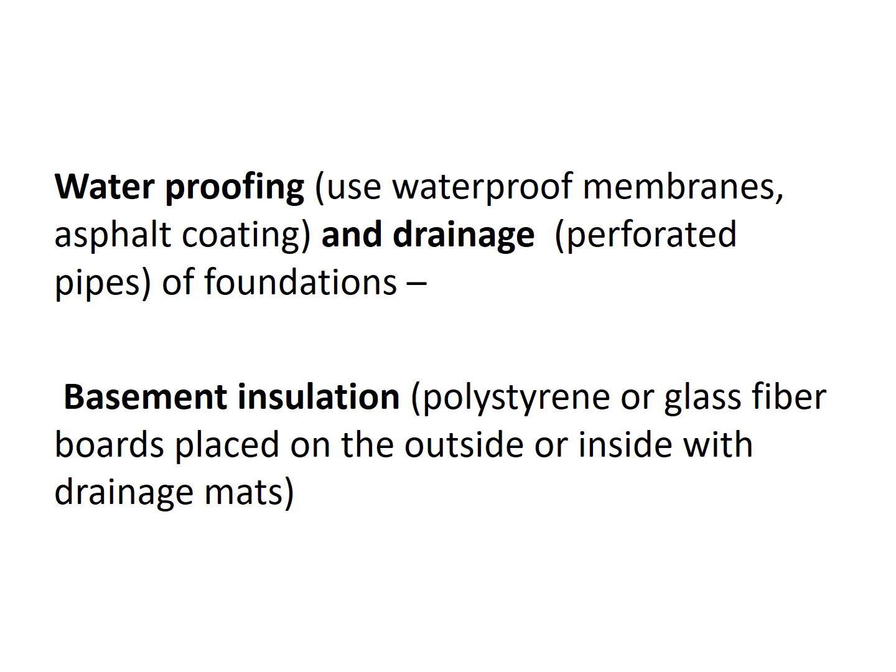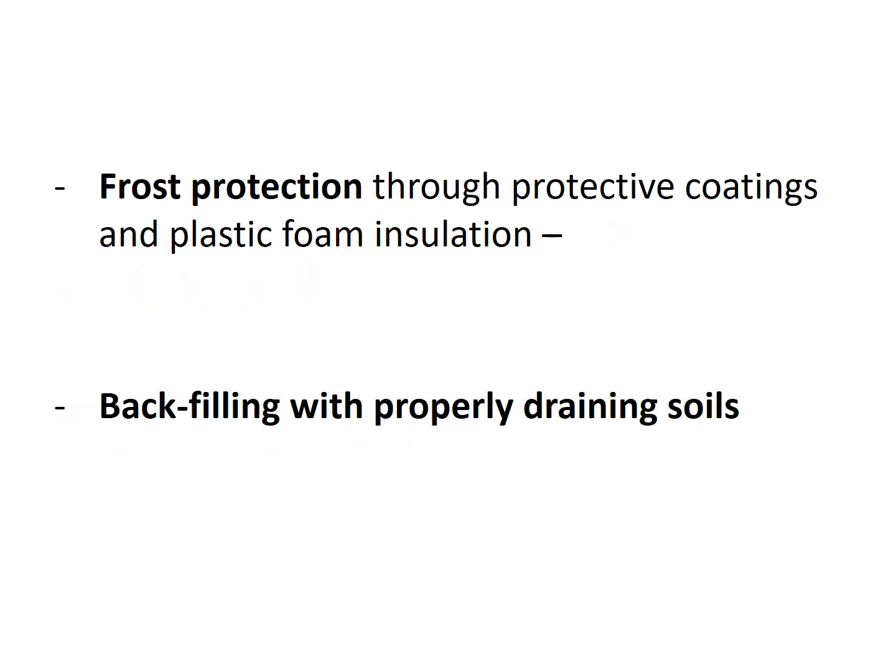Now the basement insulation, which is another item of foundations, where polystyrene or glass fiber boards are placed on the outside or inside with drainage mats. Another item of consideration is frost protection through protective coatings and plastic foam insulation. And the most important is when you come to the end of the process to backfill against foundations with the properly draining soils.